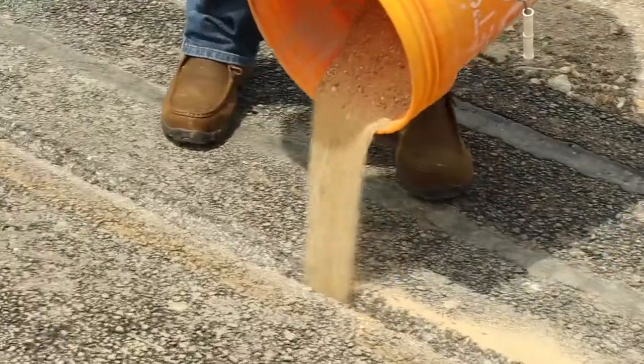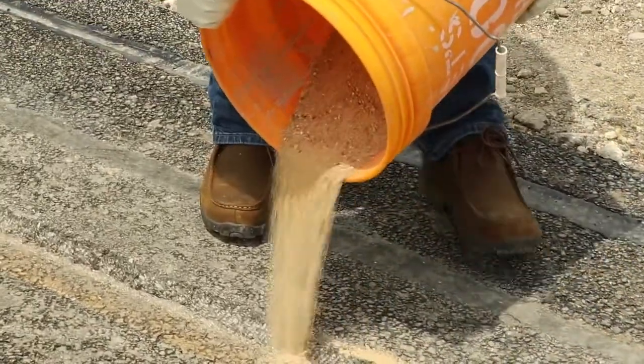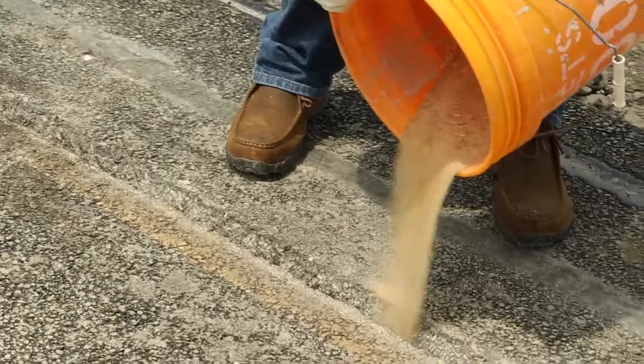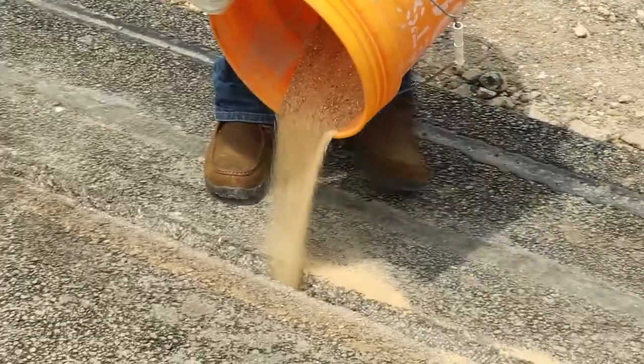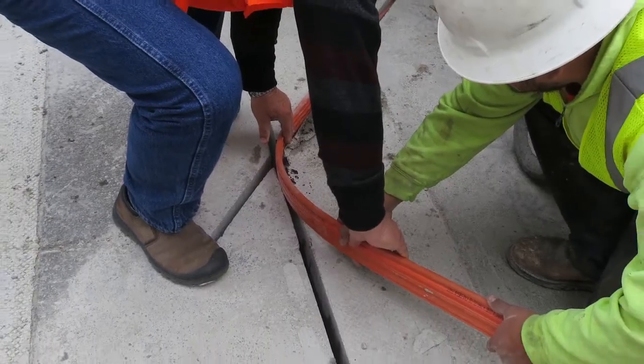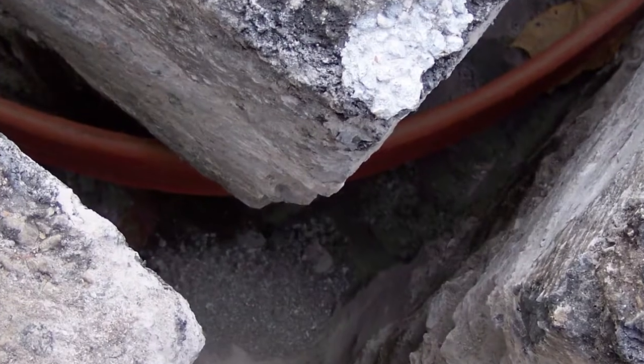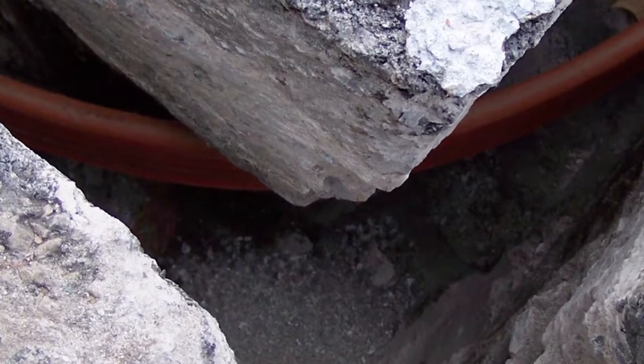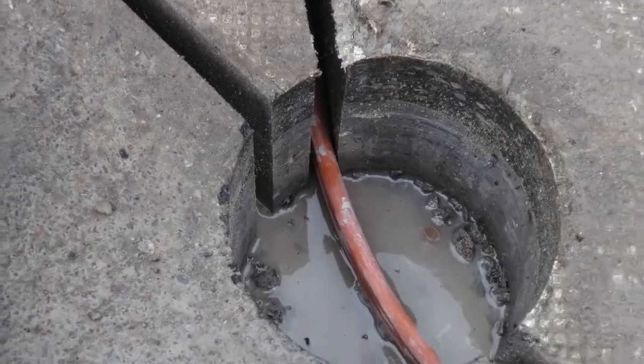If the trench is rocky, placing a layer of clean sand into the trench will help prevent sharp rocks from deforming the microduct over time. If the route requires a turn, make several gradual cuts and, if possible, undercut the corners so the microduct bend radius is not exceeded and it transitions with a natural bend.